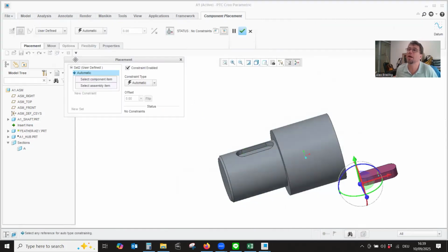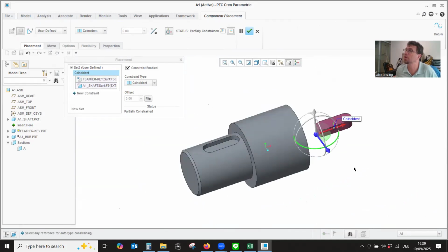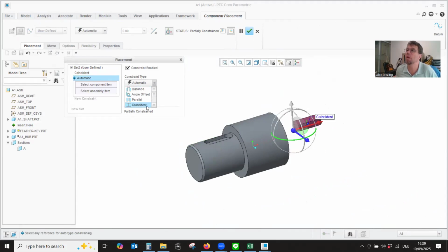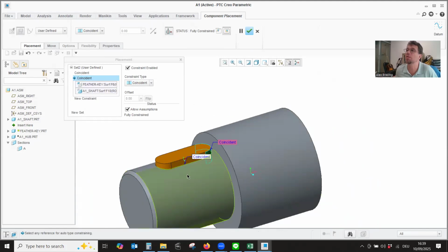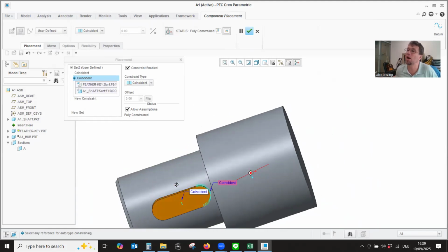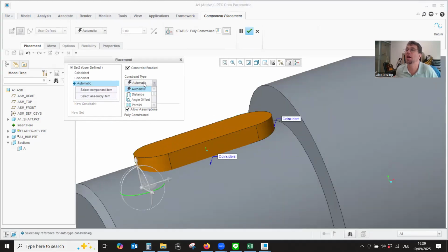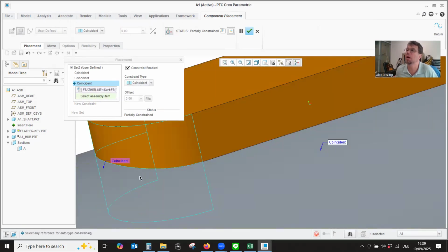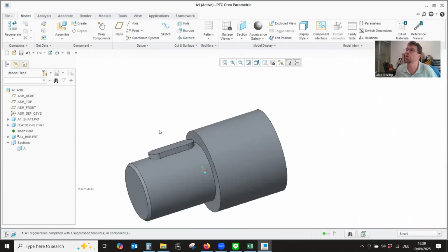Snap. And there are many ways to do that. I would actually use the actual component surfaces. So surface on surface. And now I can actually coincide these partial cylinder surfaces. Now don't allow assumptions. Don't allow that. Explicitly fully constrain it. So think about how many constraints you need. So I'm aligning both cylinders to make 100% sure this is what's going on.